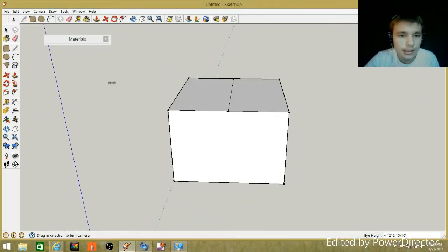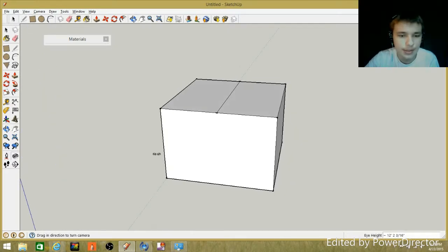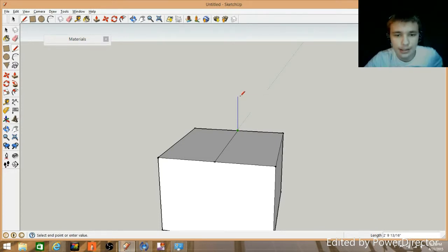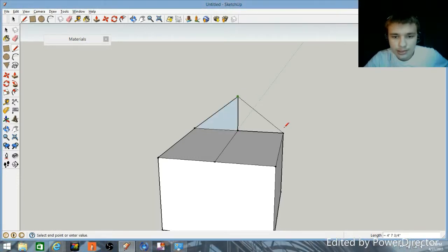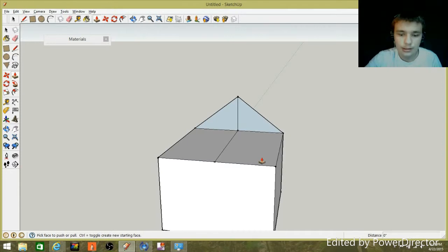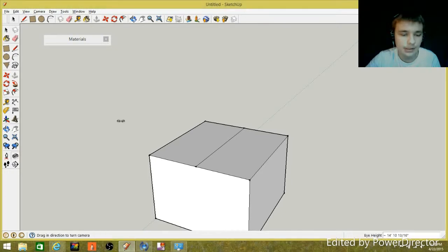And then to raise it, there are 2 different ways of doing this. You can do it this way, which I think is the harder way of doing it and takes a little bit more time. You can just draw your center line up. So you could connect these 2 points, and then go ahead and delete this line, and then just bring this across like so. Or the way that I like to do it, the way I always typically do it, is this way.